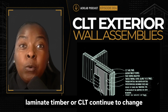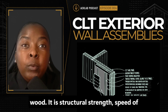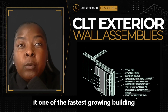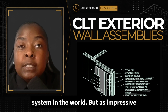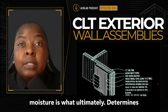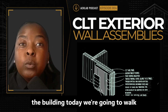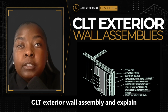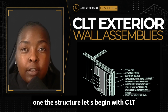Cross-Laminated Timber, or CLT, continues to change the way we think about building with wood. Its structural strength, speed of construction, and sustainability have made it one of the fastest growing building systems in the world. But as impressive as CLT is structurally, protecting it from moisture is what ultimately determines how well it performs over the life of the building. Today, we're going to walk through the layers of a high performance CLT exterior wall assembly and explain why every single layer matters. So, layer 1, the structure.